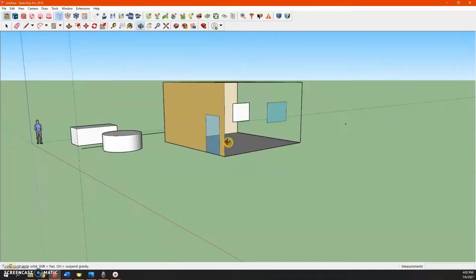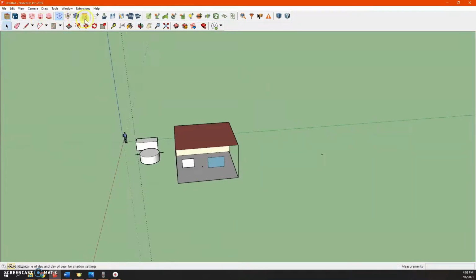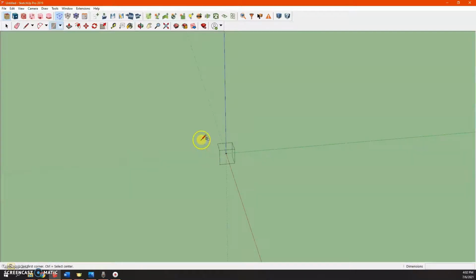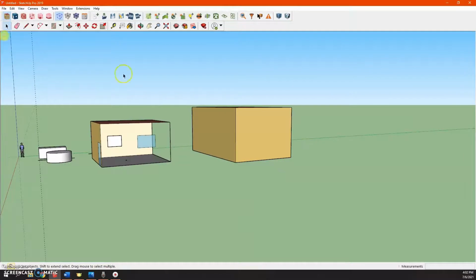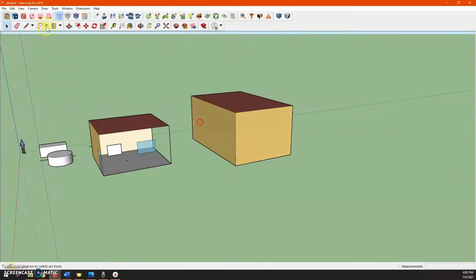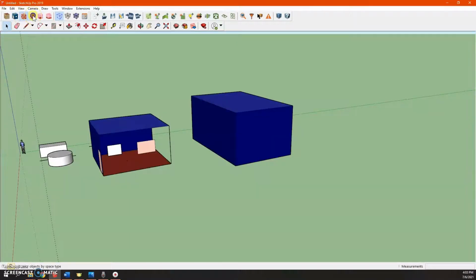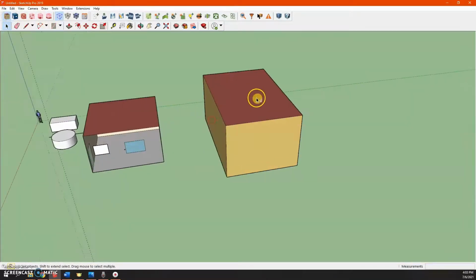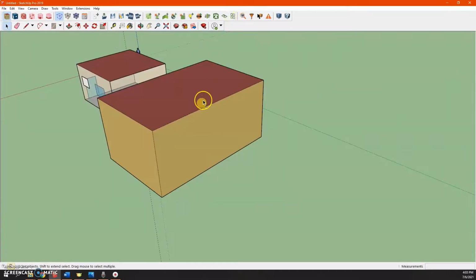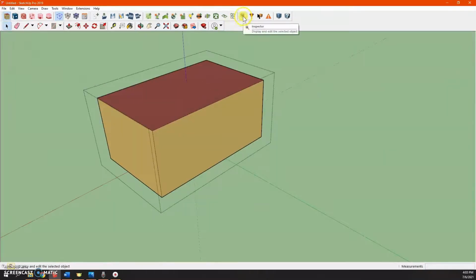So now I want to show you all the different rendering modes available in the SketchUp plugin. Right now I will create this new space, just like another typical room. The default render is render by surface type. To the right we have render by boundary condition. After that, render by construction, render by space type, render by thermal zone, and then render by building story. As you see, all these different render modes have different colors, and these colors are the ones defined in the actual OpenStudio application.